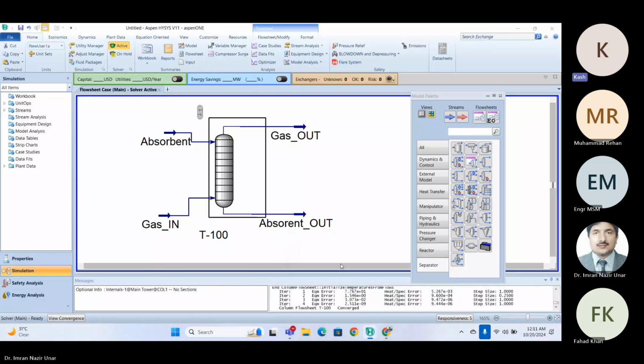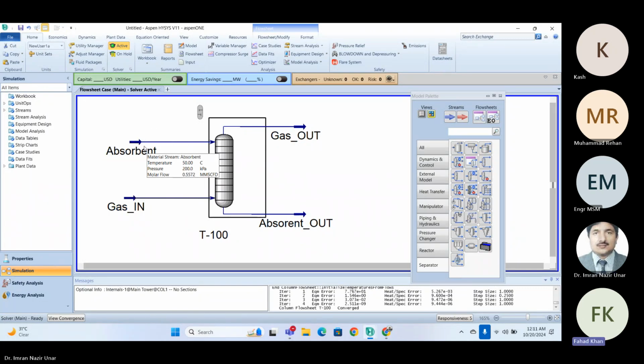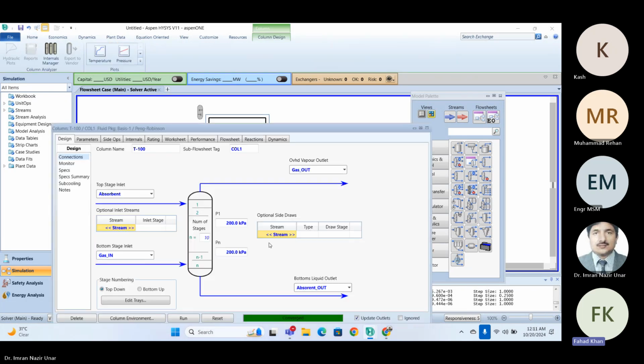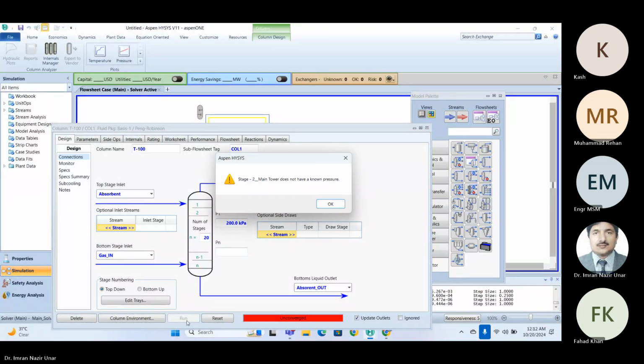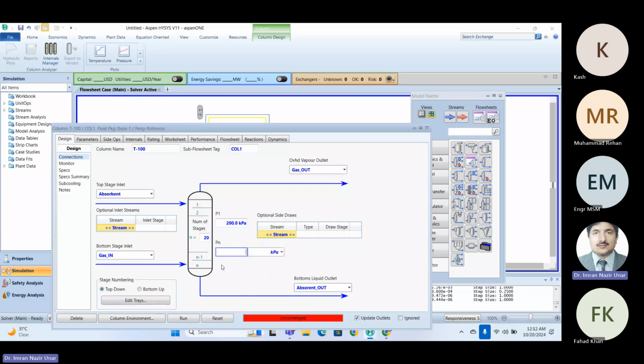Maybe increase the pressure? Increase the pressure of what? Maybe we can increase the contact area between the gas and water. The tray height at 10, which you specified, if we increase it, for example to 20, the surface area and contact will be more.